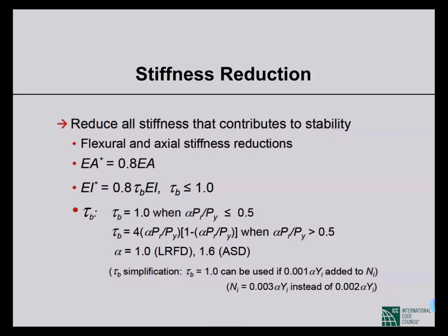So that is important. And remember, during the process of deformation, the axial force values vary, and usually the software, in every increment of deformation, calculates the amount of axial force that's coming onto a particular member, and incrementally the flexural stiffness is adjusted. Okay. So that is it.